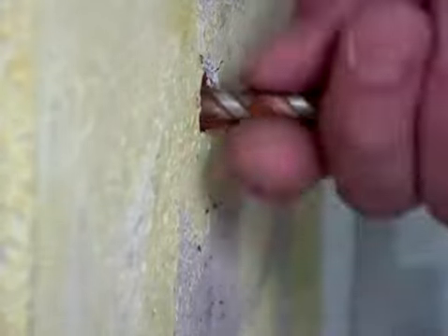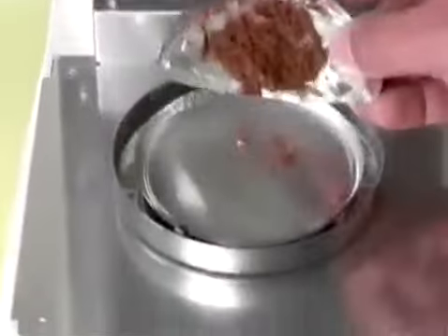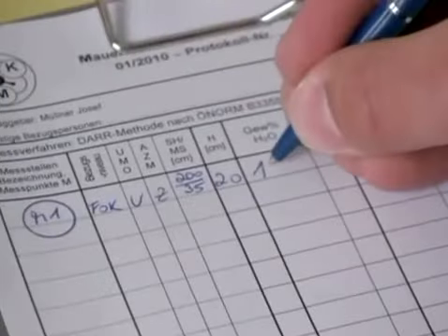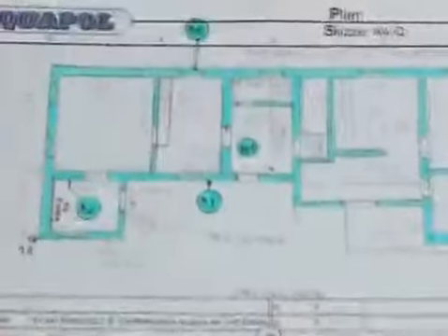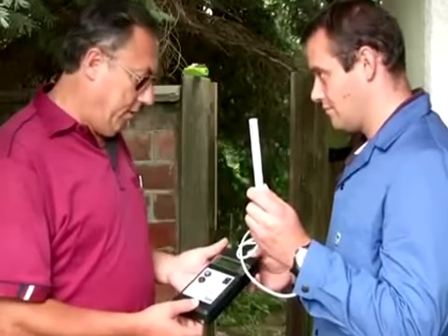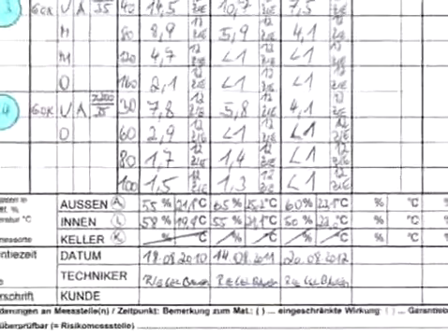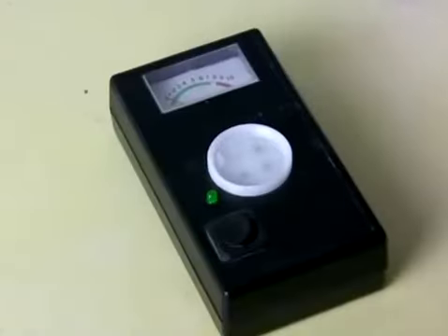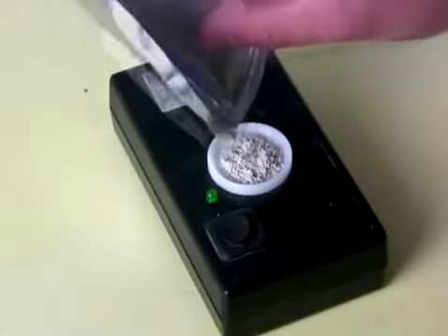Moisture measurements are carried out according to the scientifically accepted DAR method at places determined in agreement with the client. This laboratory measuring device guarantees highest precision, fast determination of moisture content on site, and maximum objectivity for the client, and the results are noted in the measurement report. Climate data from the outside and the inside, as well as the degree of salinisation of plaster and masonry, are recorded. Diagnostic investigations of masonry provide further information about the condition of walls.